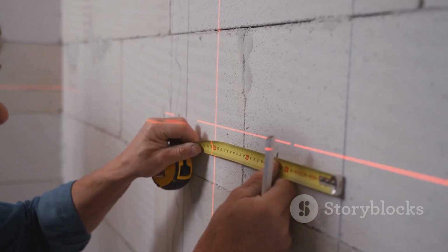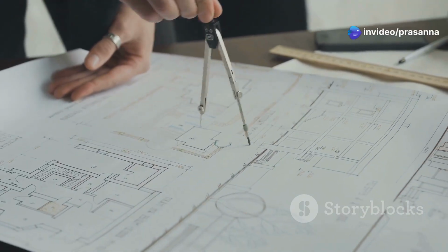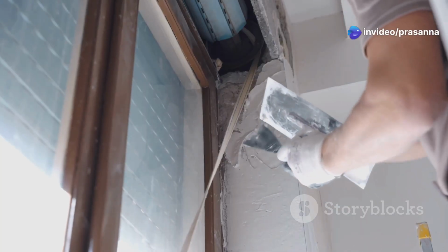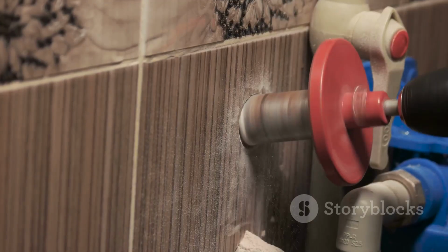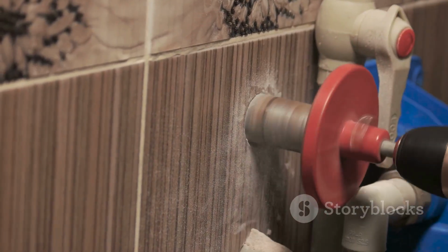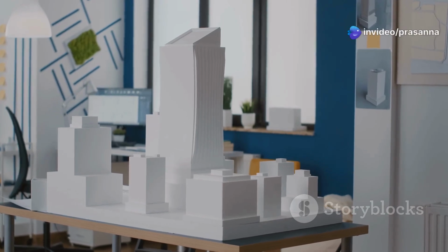First, use the Tape Measure tool to create guidelines. These guidelines help you place the openings accurately. For example, you can set the height of the windowsill and the top of the door. Once you've drawn the rectangle for an opening, use the Push-Pull tool. Push the surface inwards until it meets the opposite face of the wall. This will create a clean opening.